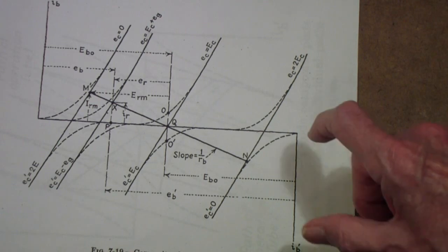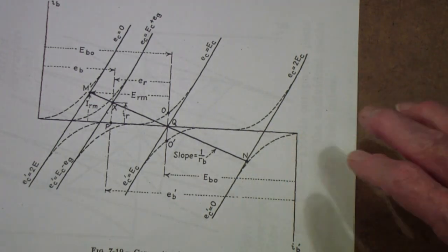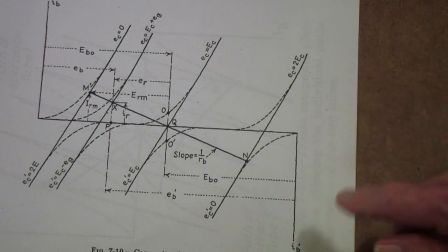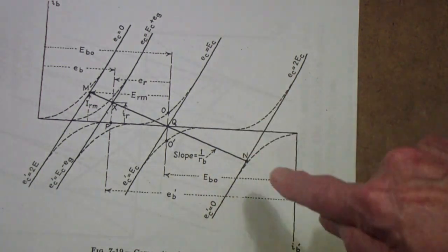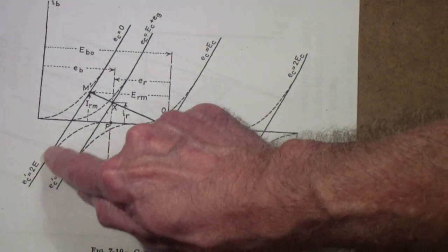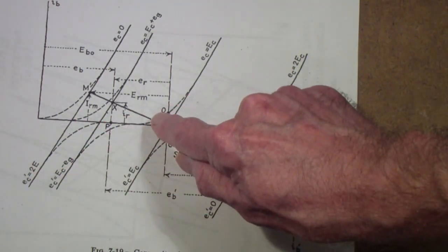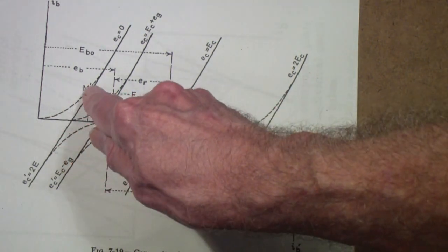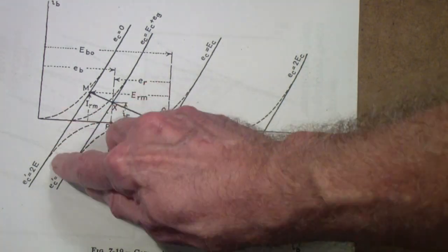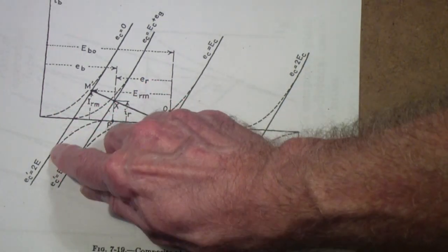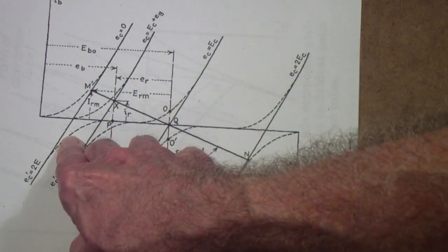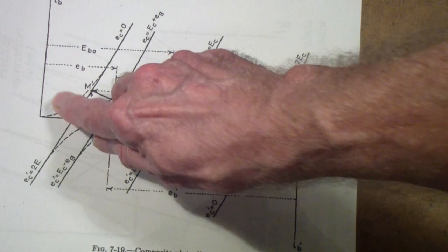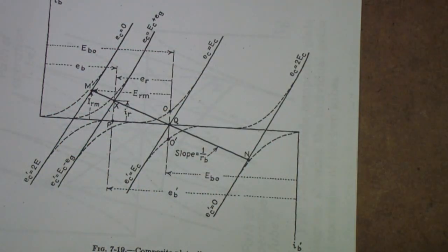But because they are connected out of phase with each other, 180-degree phase reversal, what happens is the composite, instead of having these curves that a single-ended tube will have, the curves tend to match each other. Notice that this curve and this curve, if you add them up, what you find is that as this one starts to curve over and slow down in terms of its speed, this one speeds up. So it's almost like you have, well, maybe I shouldn't go there, spooky action at a distance.